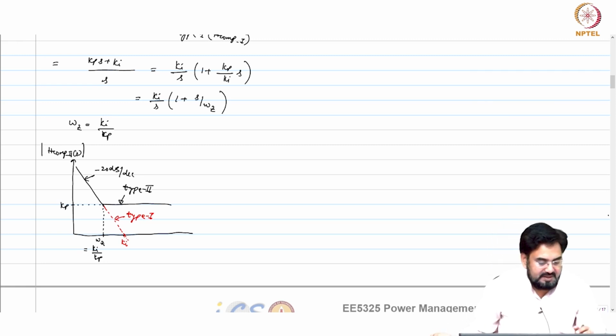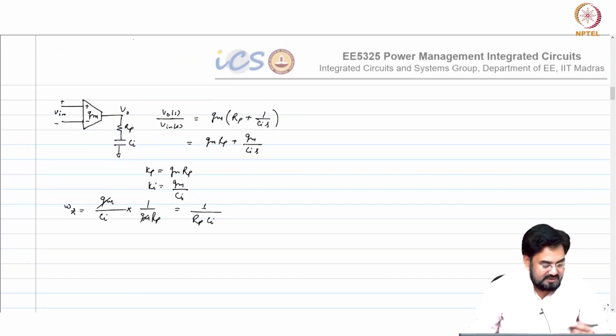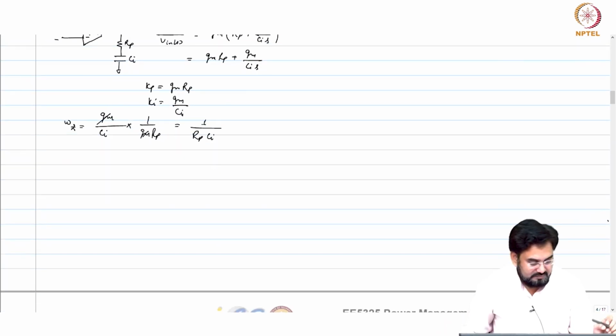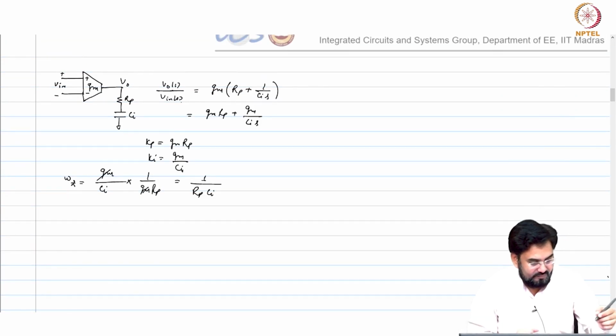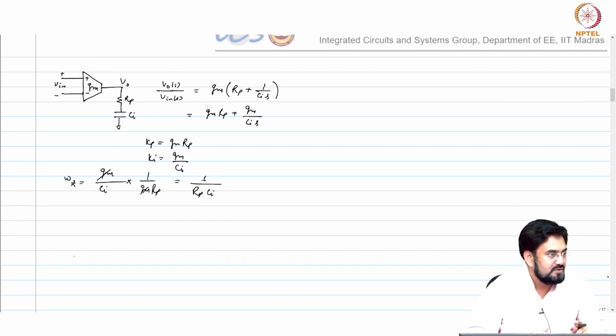But we want to independently change the proportional term, which you can only achieve by changing the R. And moreover, we want this 0 to appear before your resonance happens, otherwise you will not get any benefit. So you can place this 0 according to your Rp.